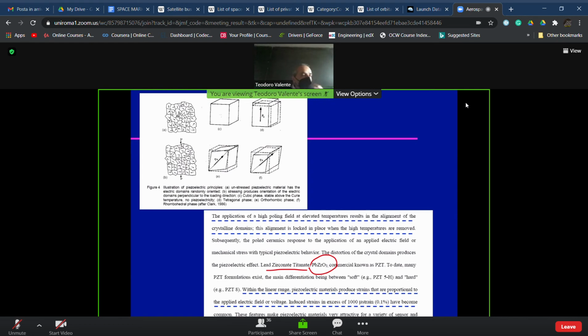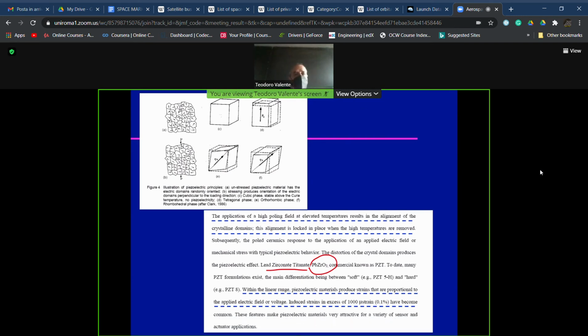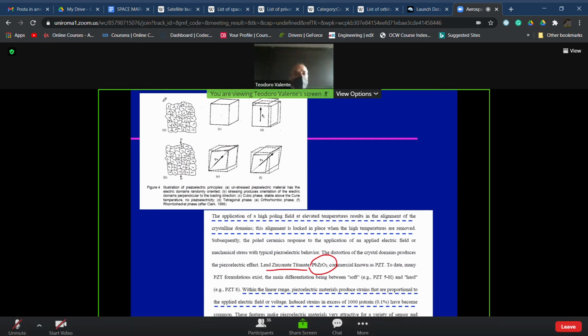In a classical configuration, dipole orientation inside grains is random, so there is no resulting polarization vector. The ceramic materials which can exhibit a piezo behavior can be conditioned so that all the dipoles are equi-oriented and thus result in a polarization vector, which is the reason why the piezo effect can appear.